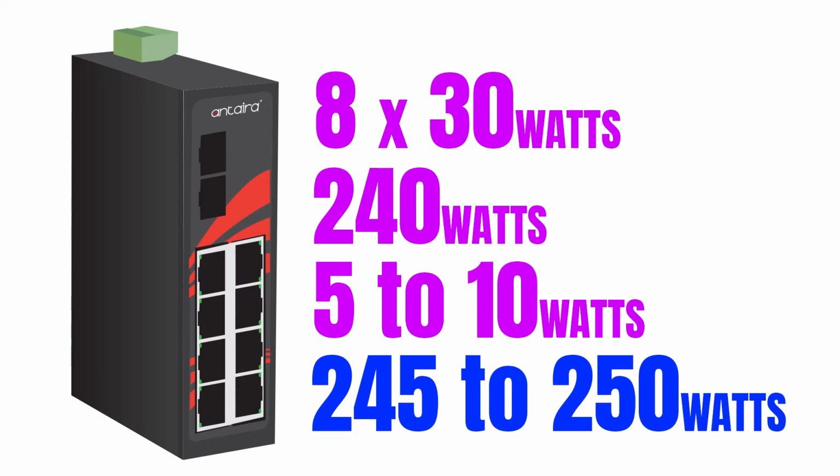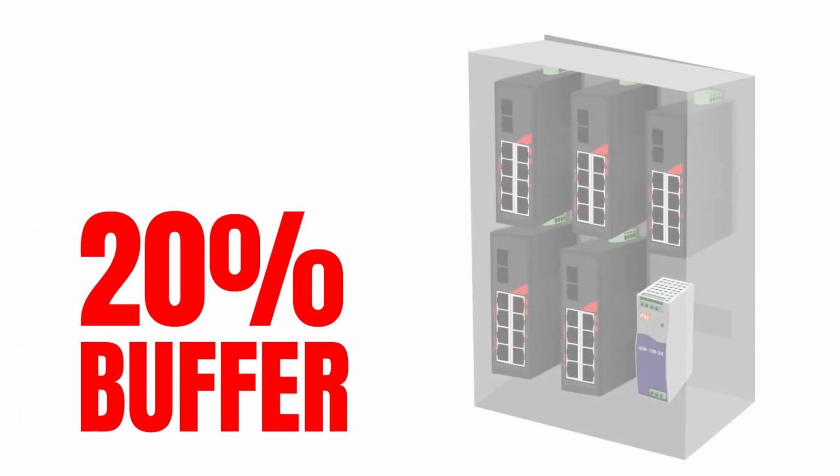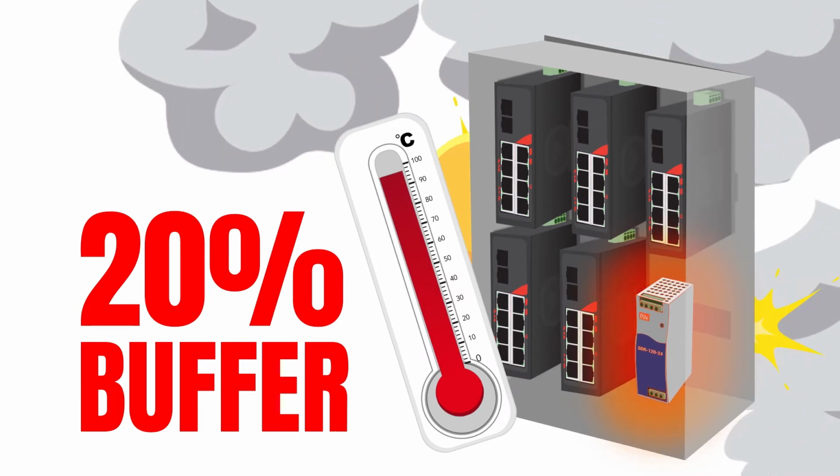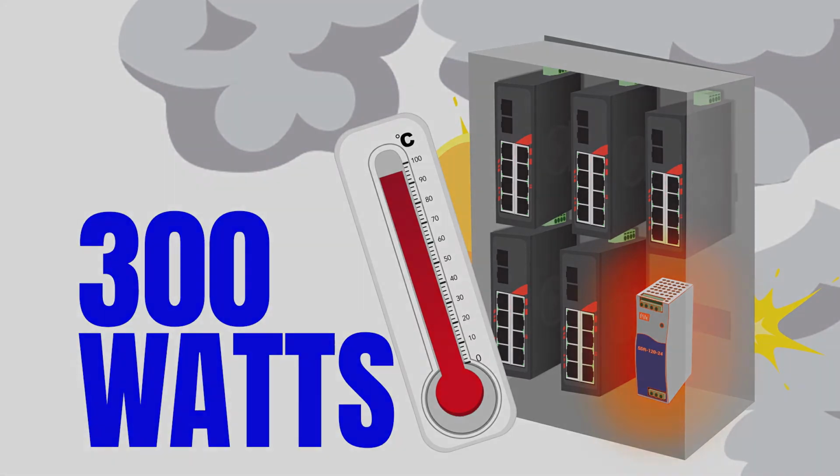You typically need to add 20% because most DC power supplies will degrade if the temperature rises above 50 degrees Celsius. So it is best to give yourself a buffer. This will bring the requirement up to around 300 watts.